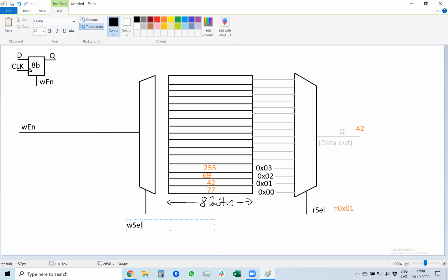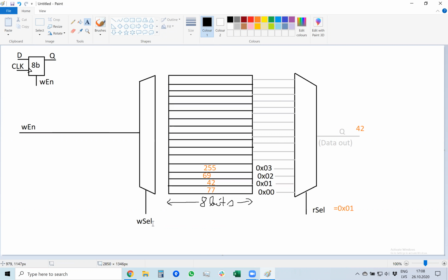And with this, we will just forward this write enable to one of these many cells. So for example, if I set write select equal to 3, then write enable will be forwarded to cell 3. All other cells will be equal to 0. So all other cell write enable signals will be equal to 0. So they will be disabled for writing, and only this one cell, for example, cell number 3, will be active, and it will receive this write enable signal.